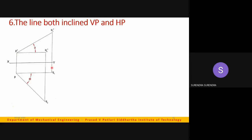So this is when a line is inclined to horizontal plane with an inclination theta. Here it is represented as P, P dash, P and Q, and on board I have shown it as AB. So when the line is inclined to only horizontal plane, we'll get this trapezium shape. True length of the line, P dash Q1 dash, inclined at an angle theta with the horizontal plane. And when the line is inclined to vertical plane, we'll get a shape like this. Depending on the dimensions and the angles, in some cases Q2 dash is inside, and in some cases Q1 dash is inside the figure. So don't confuse, it is just a representation, and this is not as per the dimensions.